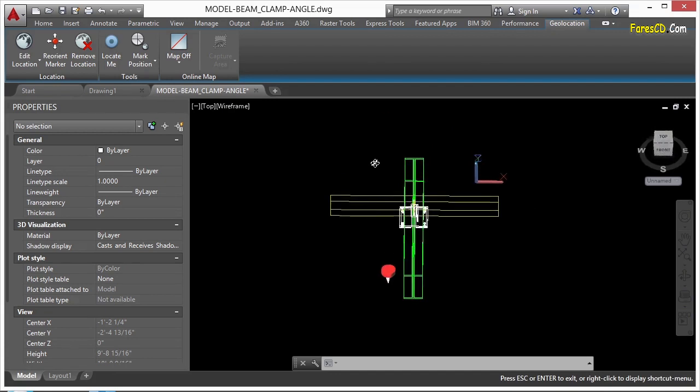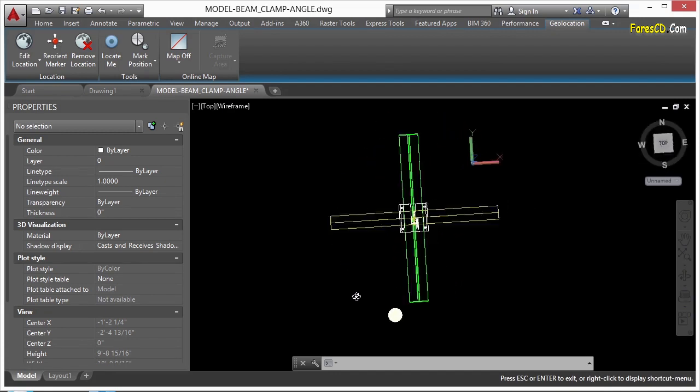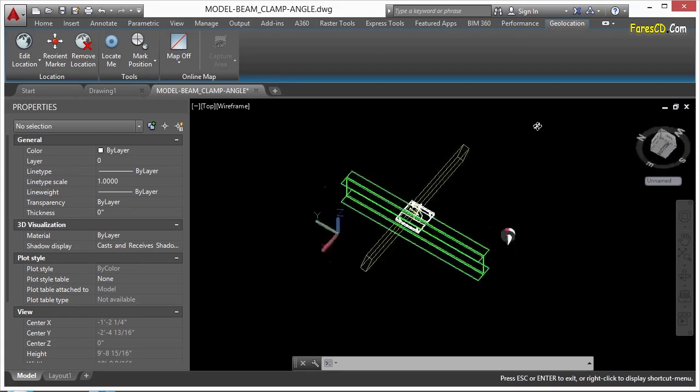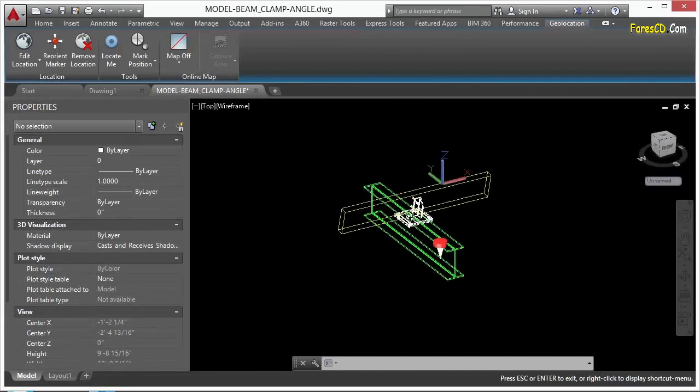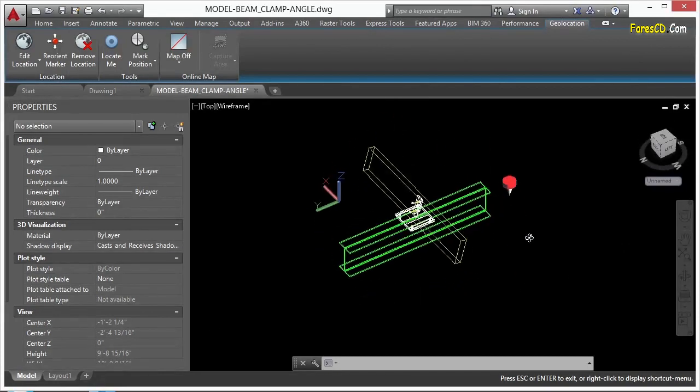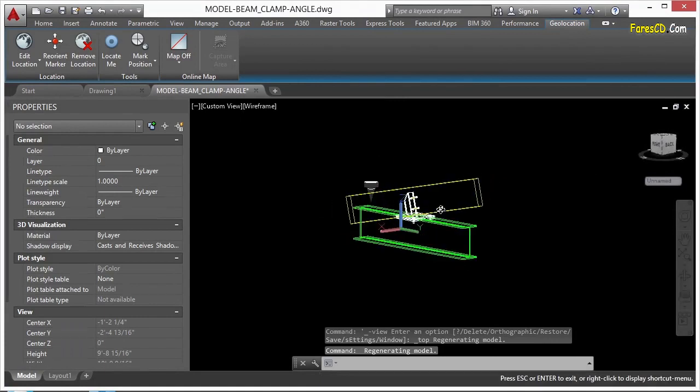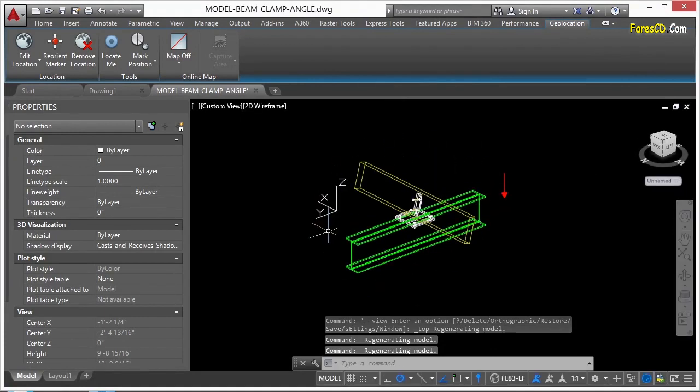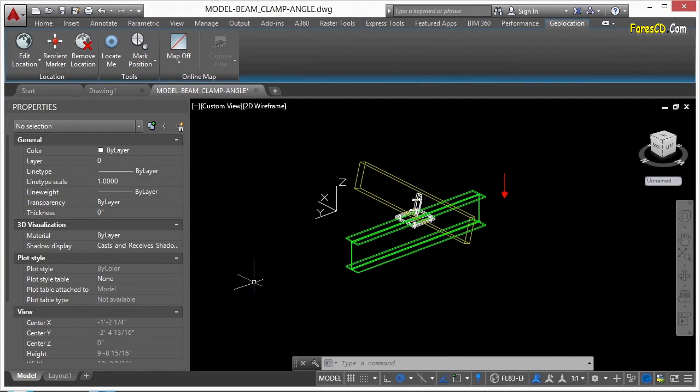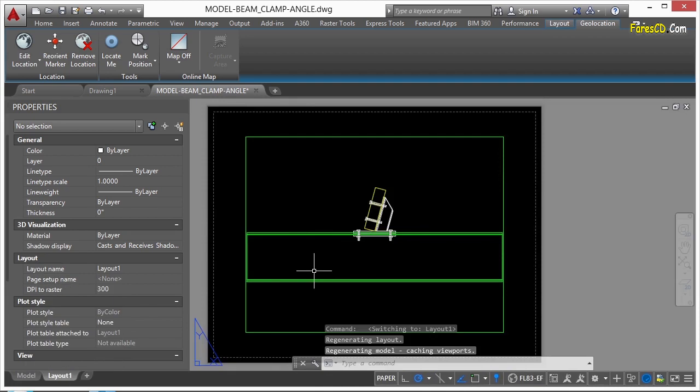That'll rotate it. And if you move it up and down, it'll rotate it this way. If you do it in conjunction, it'll rotate them in multiple different axes at the same time. And so this is a great way to get a different view of your drawing. Now, where 3D orbit is fun, it lacks precision. And you can use it in any view. You can use it in model space, or you can go to paper space.